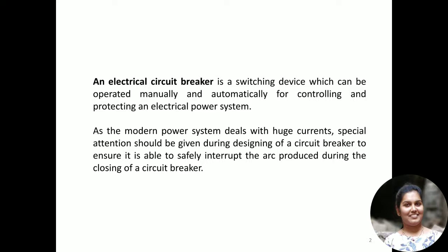That is, here the replacement which we see in case of a fuse will not be seen in case of a circuit breaker. That is, when a circuit breaker comes into action, it will work, and again come back to its life, and it again starts working. Whereas in the fuse we don't see this kind of thing. Like, once a fuse is blown out, we have to replace it with a new one, or a wiring again should be done to the fuse. In case of circuit breakers, we don't see such kind of thing.